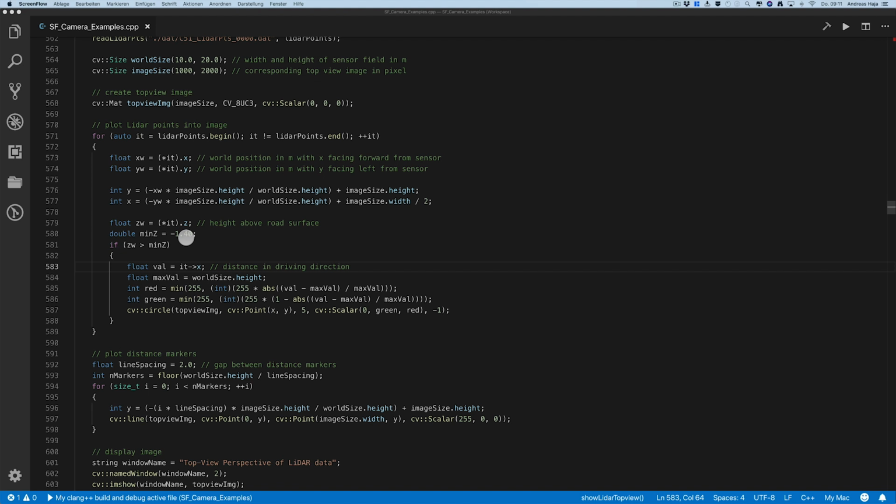It's quite interesting because when you change this value and, for example, imagine a car with a certain width, you have basically a point cloud representing this car, and it narrows down while you get to the roof, because the widest perimeter of the car is approximately on the height of the tail lights. And if you adjust the scan width or the height, the min z variable, to a setting, for example, let's say minus 0.8 centimeters, what you will see in the resulting top view image is that the car which you scan actually gets narrower because you move upwards in the respective z threshold.